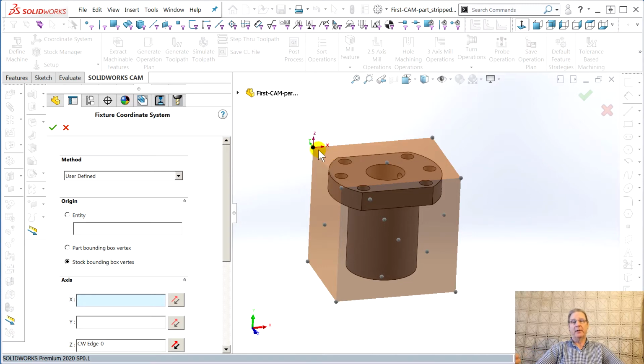Most machinists prefer it on the left, because then they put a tool stop, a work stop gizmo, to the left of the vise, and they slide the stock on, it hits that stop. It causes some problems because a lot of engineers want to think of X being in this corner and going down, but that's not smart. You want the part 0 to be referenced to the fixed jaw of the vise. So that's back here. This goofy thing, normal stuff.